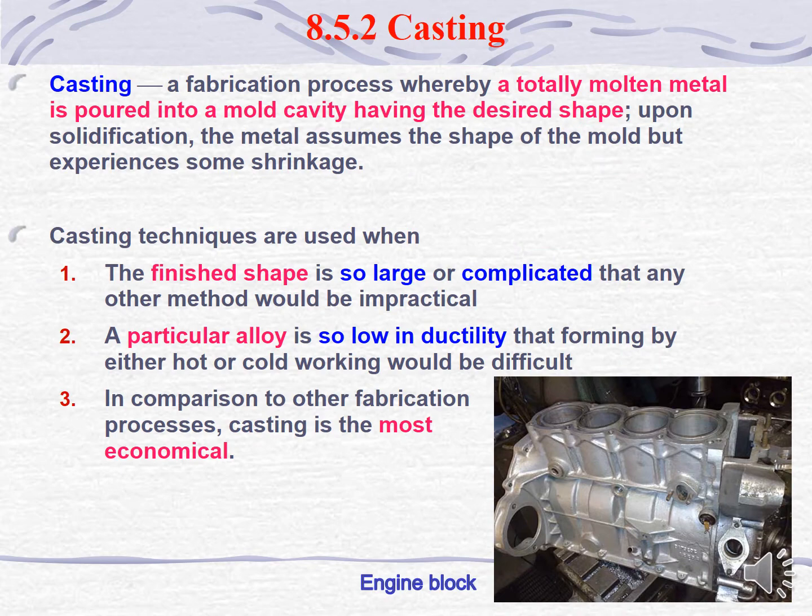Now we move to the casting process. Casting process is a fabrication process whereby a totally molten metal is poured into a mold cavity, which has the desired shape. Upon solidification, the metal assumes the shape of the mold, but at the same time will experience some shrinkage.